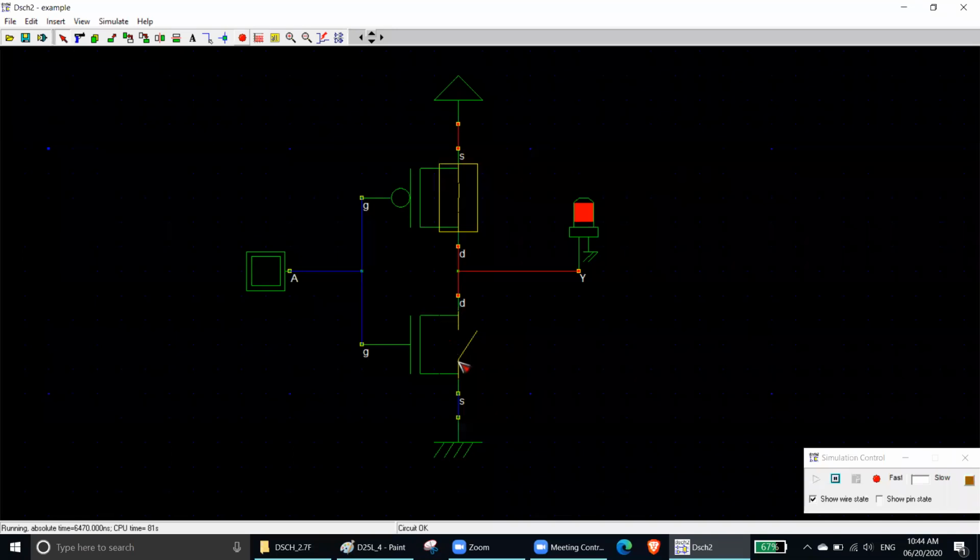Okay, so if it is open circuit, it cannot go, but it has to go somewhere, somehow. So what it will do, it will go inside of the LED, then it will come out, it will go to the ground now. So current will come in this way, it will go through the LED, then to the ground. So when the current goes through the LED, it lights up. That means it is 1. So when your input is 0, your output is 1.